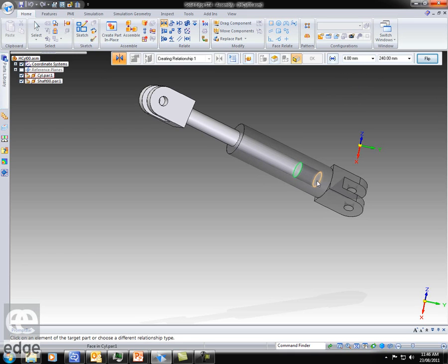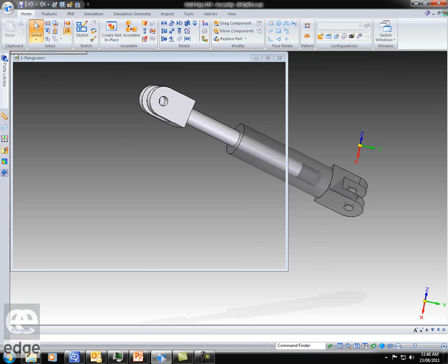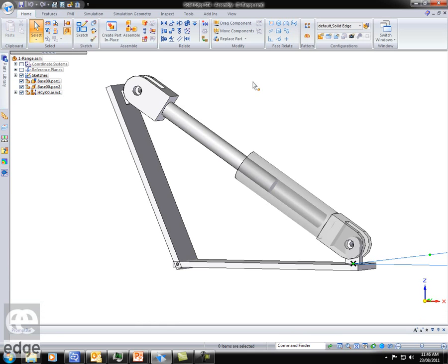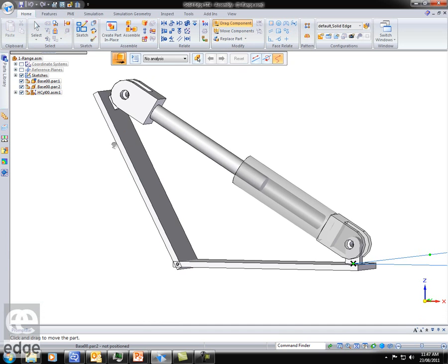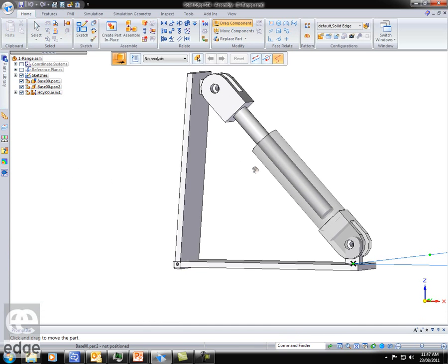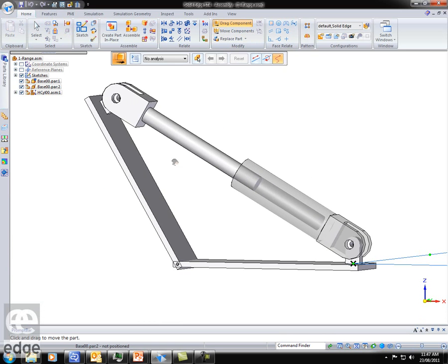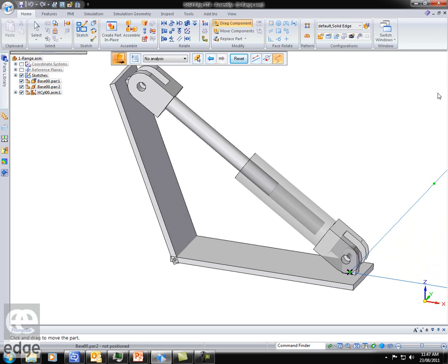And the other end of the mate is to there. Okay, save that, slip back to my assembly, and now see what happens when we adjust the assembly. You'll notice it can't travel any further there, and when I come back in here, it's 4 millimeters. So this is very nice. I like this one. Good fun. Okay, let's close that down, move on.